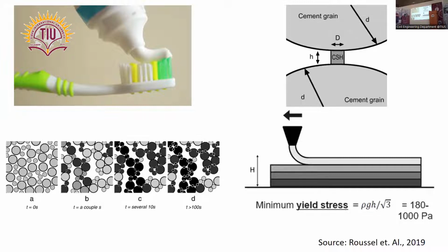He already clearly explained that when cement particles grow with time, the CSH tries to bond the cement grains, and with progressive time, more CSH will form and try to hold these particles. You can see that they have some inter-bonding, and these bonds are very poor. I mean, with application of shear force, you can easily break that. And due to flocculation of these cement particles, even if you break by applying some shear force, you can easily decrease the viscosity for pumping.